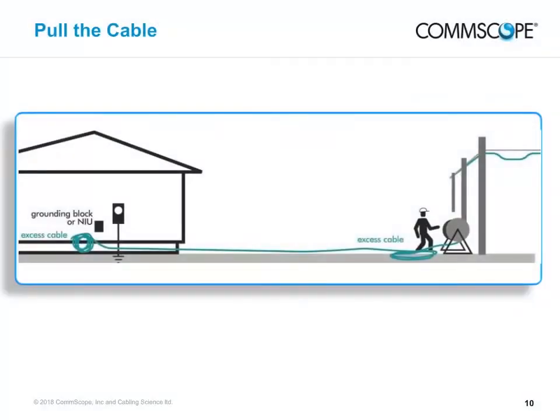Set up your cable pack or A-frame beneath the tap. Take the cable end and walk toward the attachment point. Don't let the cable kink, scrape, tangle, or get hung up as you walk. It may deform the cable and cause transmission problems later. Keep pulling cable after you reach the attachment point. Remember, you need to have enough cable in hand to run along the soffit or foundation line of the building to reach the grounding point.